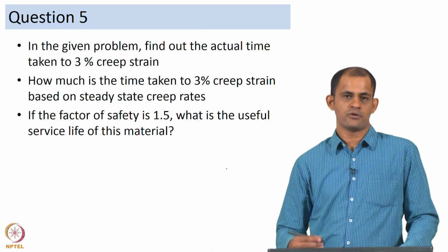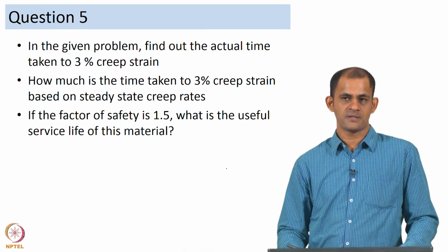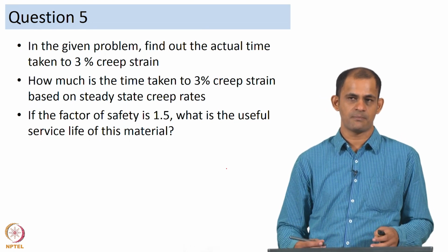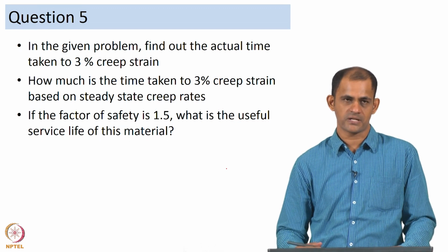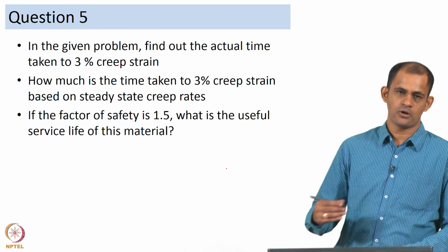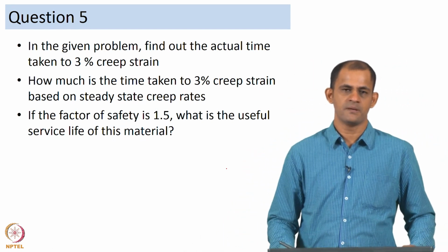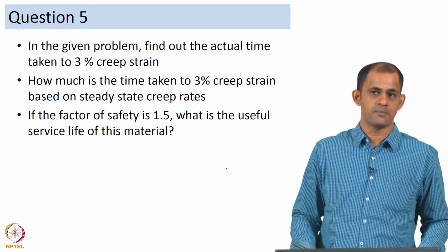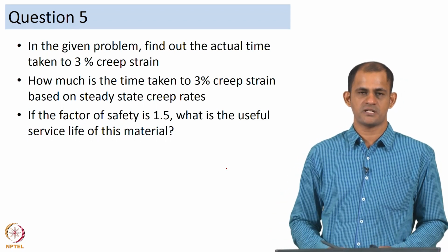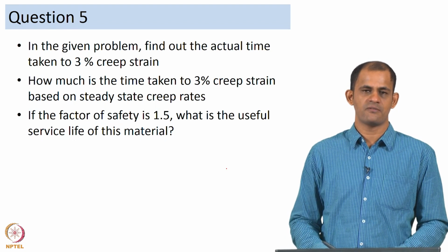If your program is accelerated, in the sense you are trying to develop a product quickly and you want to know the behavior of the material in quick time, you cannot afford for the material to go till failure, because in that process you are going to spend months of time just to get a basic understanding of the creep behavior of the material.